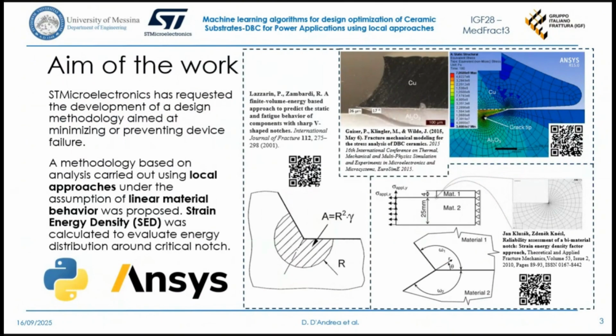Before talking about the methodology proposed to ST Microelectronics, we have to focus on what was made before, and we started our analysis by searching for works applying fracture mechanics in these components, and we found the work by Geyser, in which an experimentally measured crack in the alumina was modeled by finite element method and simulated to understand how it propagates